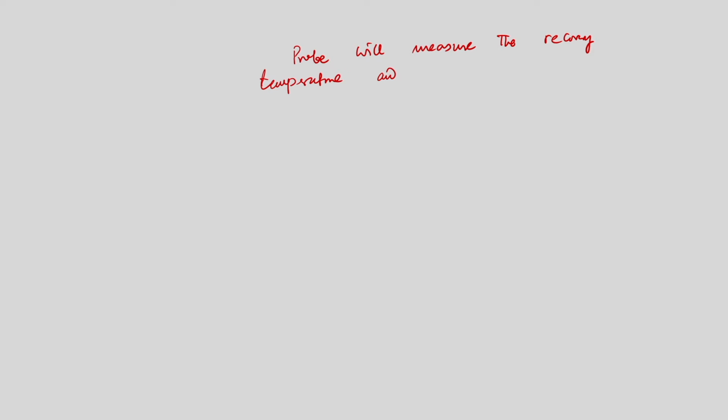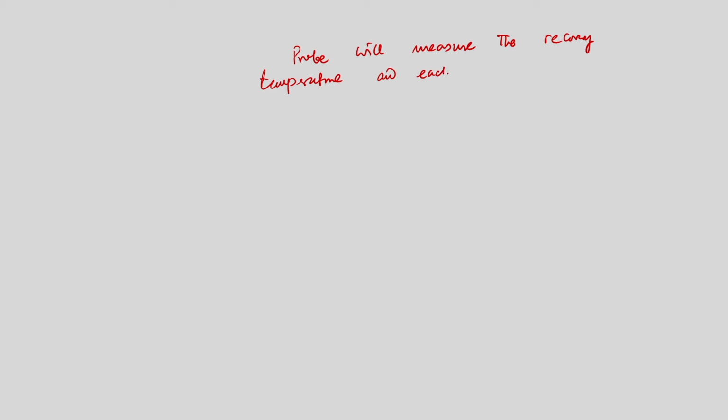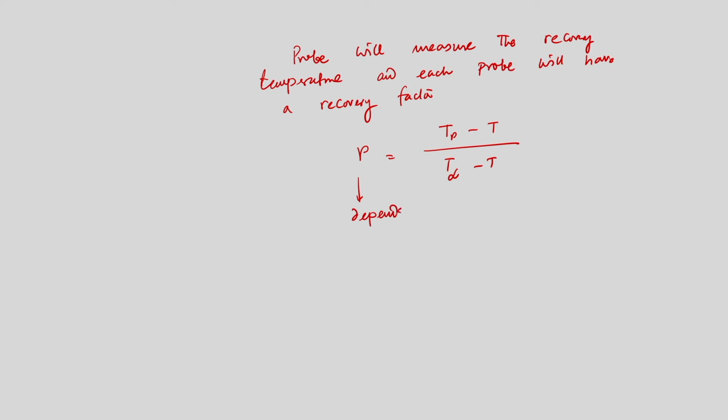and the recovery temperature should be related with the static temperature using a factor, and each probe will have a recovery factor R, which is nothing but T R minus T divided by T infinity minus T. So, this R depends upon the probe configuration.